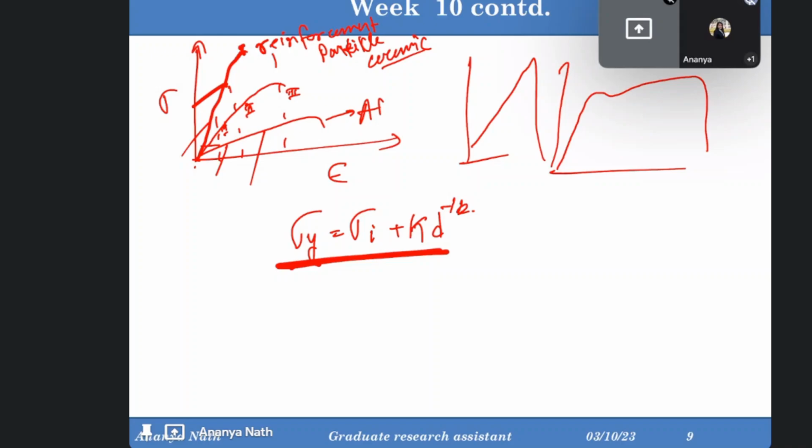And if it's elongated, then to get the original shape and size, you can just reload it in the opposite direction, or if there is a gap between the original and the elongated strain, then to fill that gap you can just pull it in that direction to accommodate the misfit strain, because there will be a high dislocation density at that region.